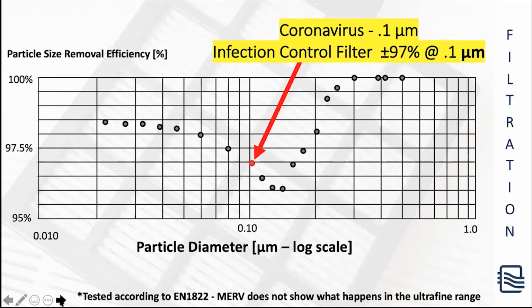Now, the really important thing though is that if we're going to have that high of a level of air filtration, the level of restriction on airflow has to be low enough that we will not cause any negative impact or unintended consequences by improving the level of air filtration that high. And it's possible with this new type of filter. So in addition to that filter being able to capture smaller particles, we can look even beyond that 0.1 microns all the way down to sometimes 0.003 microns and look at the efficiency of the air filter. That's what the testing from EN 1822 brings us.